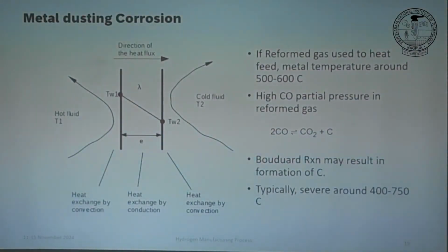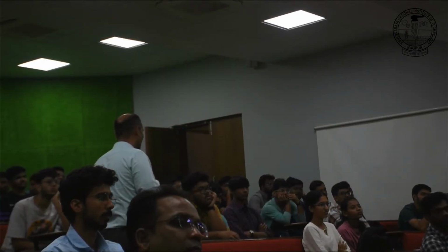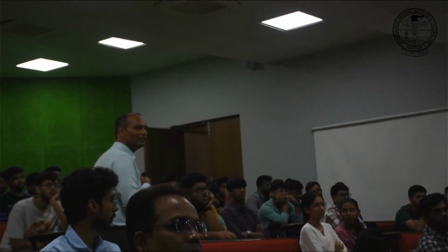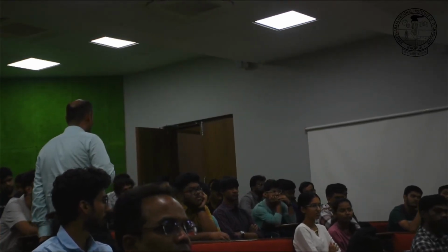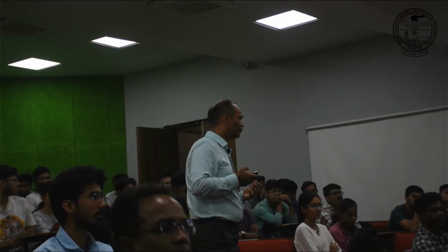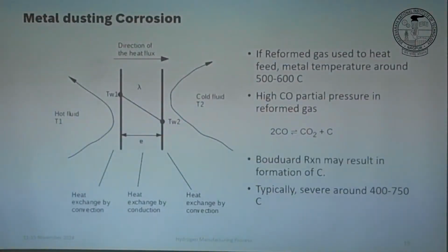Can somebody think about how we can do that? Can you think about cooling a gas suddenly? Sudden expansion. Quenching? Somebody knows about quenching? Quenching, yeah. So what you can do, you simply add liquid water, and it will absorb a lot of heat from your gas, and your metal will not see this temperature, right?